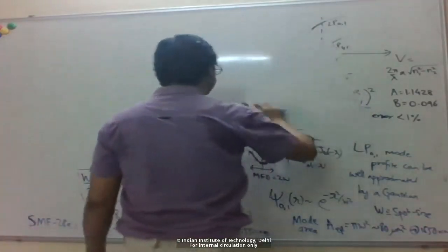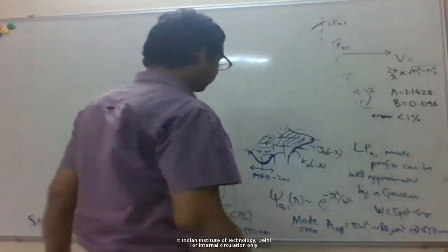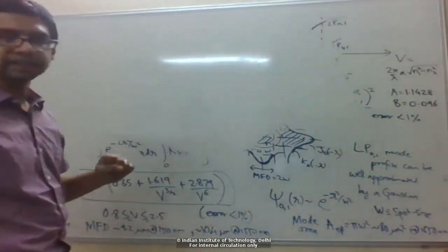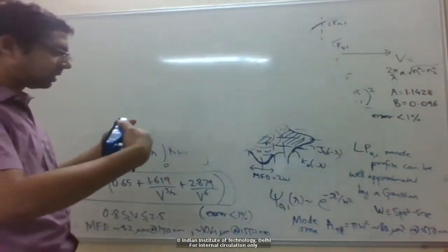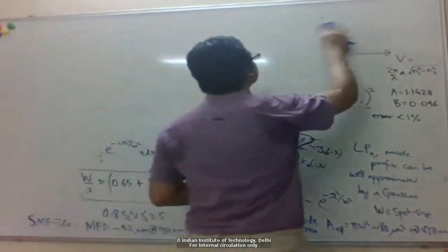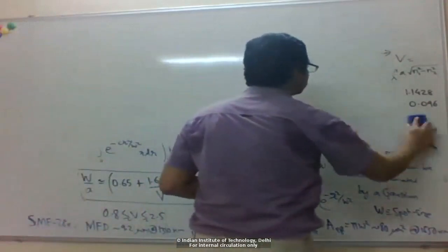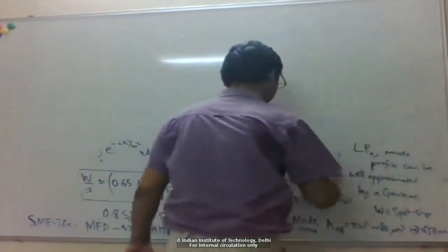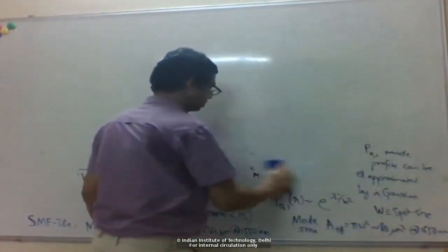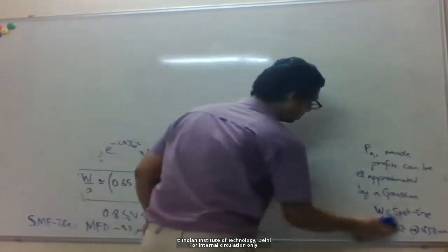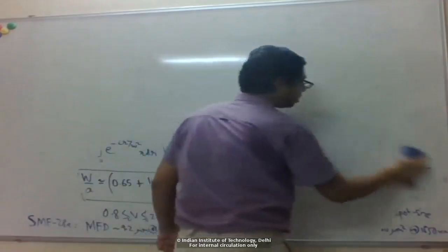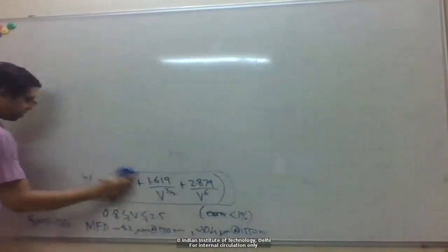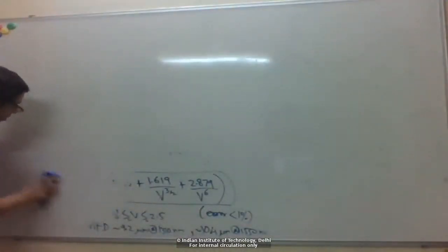But of course, we are talking about very small core sizes and mode sizes here, microns. So you can imagine that the two fibers have to be aligned very precisely, for the power to get transferred from one to the other efficiently, with negligible loss. So what are the tolerances that are allowed? We can calculate that again using this Gaussian approximation for the mode.